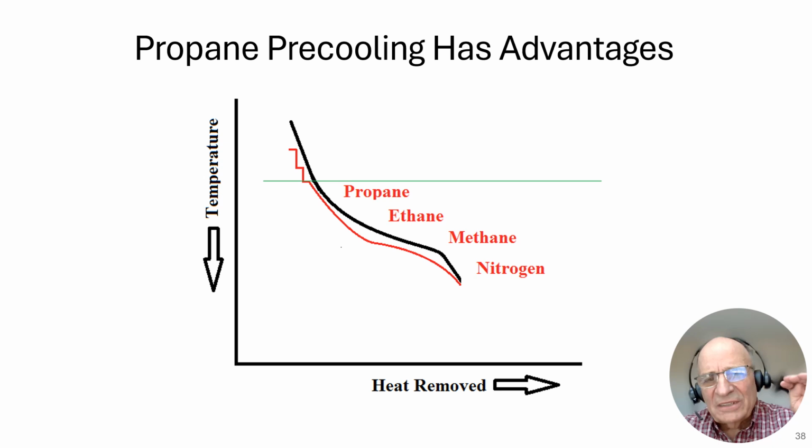You're coming in always at this fixed temperature, minus 30 degrees. And the same is true with your MR. It's always coming into the main cryogenic heat exchanger at minus 30 degrees. I just picked that number randomly. It could be minus 20, minus 35, whatever it may be, but it's going to be something that's set up by your pre-chilling system that's shown here.